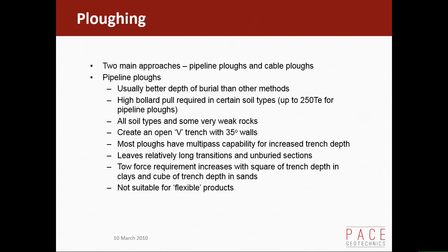I had a good client of mine who wanted to build a mechanical trencher, and they were adamant it was going to be able to trench at 1,000 metres water depth, and I said all along, you'll never use it at that water depth, and they haven't. 10 years later, I don't think it's ever been over about 200 metres water depth. And the cost impact is significant because you've got to design an umbilical to carry all that power. And then you end up with a bigger umbilical, you need a bigger umbilical winch, and it just goes on, and it's crackers.